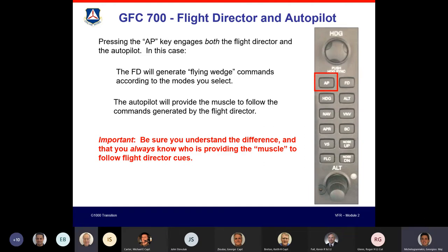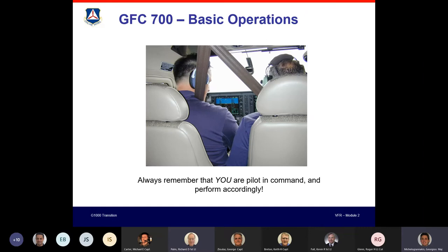All right. And then you can... Keeps whatever pitch it had when you push the button, doesn't it? You may be right. I think that's right. Okay, yeah. What I was going to lead to is that you can change both the bank and the pitch later as well with the control wheel steering button, but we're coming to that.